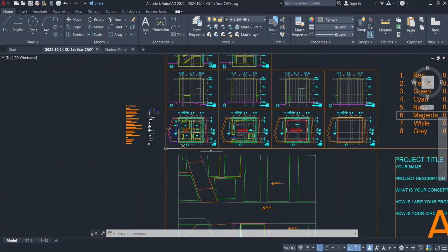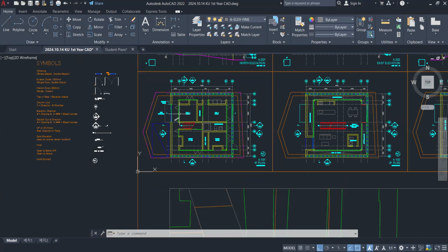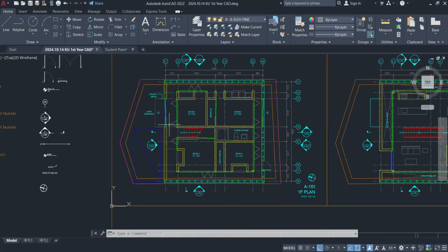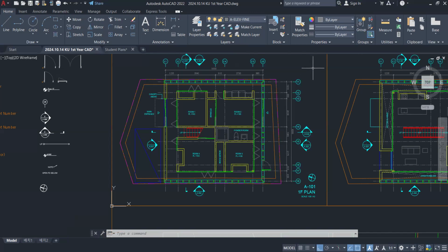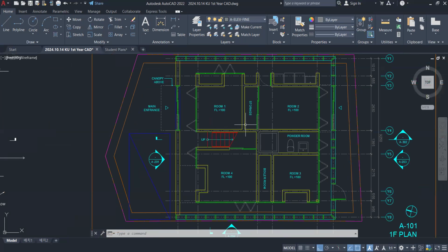Now, let's move to the first floor. On the first floor, we don't have any spot elevation markers, but on the exterior of the building, you could indicate spot elevations. You could say this spot is 25.2, this spot is 25.3, 25.4, 25.5, because your site actually slopes downwards towards the west side. So you could provide a series of spot elevations. I haven't in this particular plan, but you could add it.